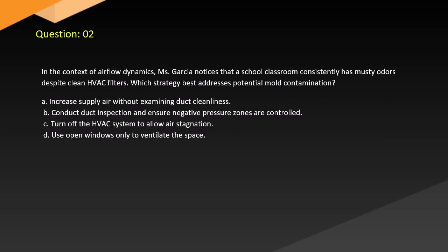Question 2. In the context of airflow dynamics, Garcia notices that a school classroom consistently has musty odors despite clean HVAC filters. Which strategy best addresses potential mold contamination? A. Increase supply air without examining duct cleanliness. B. Conduct duct inspection and ensure negative pressure zones are controlled.